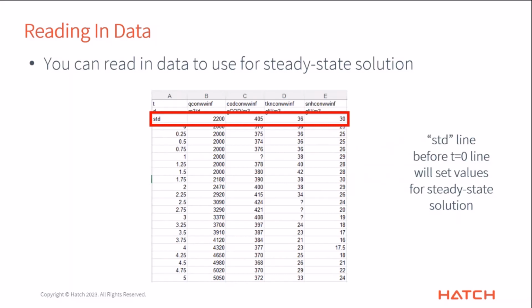So it'll use these numbers for what it does at steady state. Often, the most correct way to represent this is probably the averages of the data that came right before this. This is the equilibrium of the plant based on the loading and operation from the previous few weeks. So that's a good way to take all the numbers you had from the previous weeks, put them in and take the averages of those, put those as your steady state, and then you're starting the simulation from a good place.